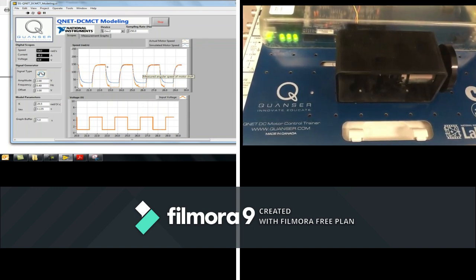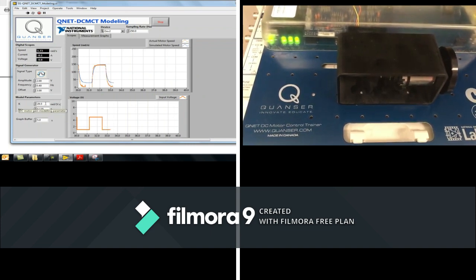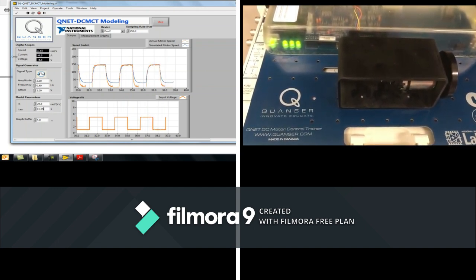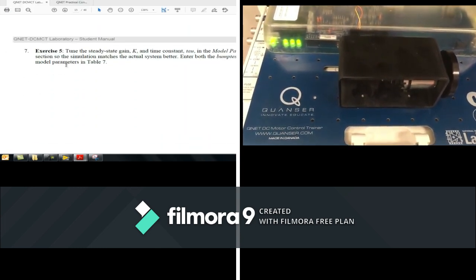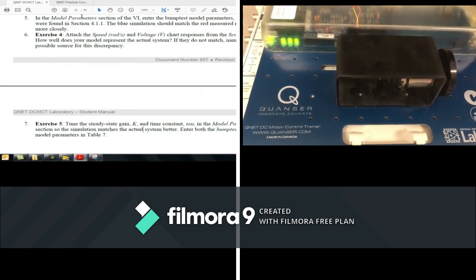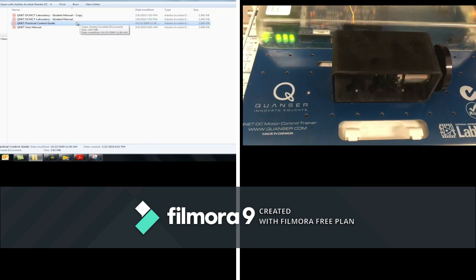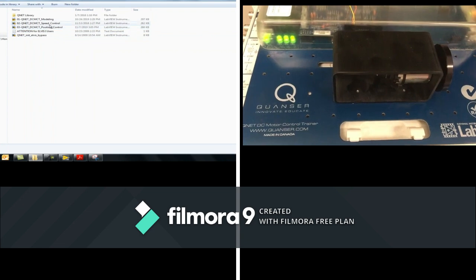So that DC motor on the screen you see has a model of a first order system, K over tau s plus 1, where the value of K is this and the value of tau is this. And this is simply the first experiment of the DC motor, which is about modeling. So this is 5 exercises, and if we go further, we will find that we can do more than modeling. If I stop this and go to the folder of experiments, VIs, I can find more than only modeling.